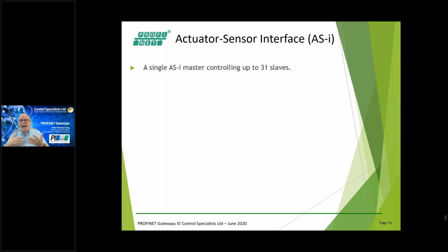So in the coming months, let's say maybe 12, 18 months, you will have a choice. You either leave the PA devices and the cabling as they are and use one of these PROFINET to PA gateways, or on a new project, you may get an Ethernet-based device for out in the plant. It's the same cabling, the same kind of cable length distances, and it will also be able to go into ATEX hazardous area applications.